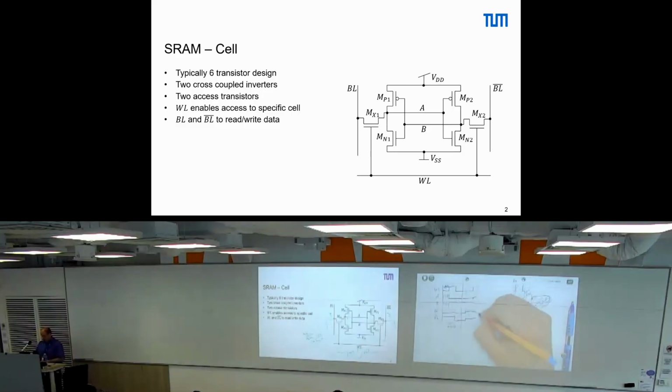This causes that we also refresh effectively our B and our A. And then we have effectively here the values you want to have everywhere, and we can disable our word line and are done. So this is effectively the read process. On a high level, you can say, okay, we just read it out. Perfectly fine from a logic perspective.